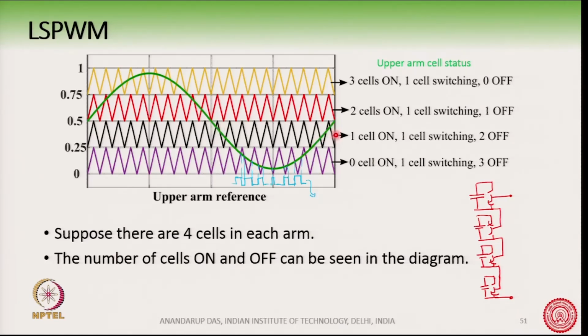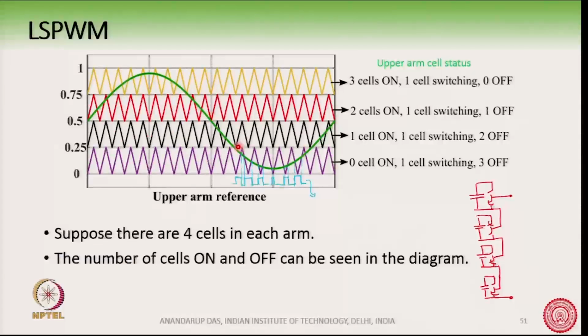but there will also be one cell which needs to be fully turned on, because it will support the waveform above this one. So, here it will get fully turned on and it will support this part of the waveform. We can assume that this is the base region and one cell, when it is fully turned on, will give a voltage of V here. So, we go one step V, over which there is a switching action here and here, which is fabricating this part of the waveform, right.